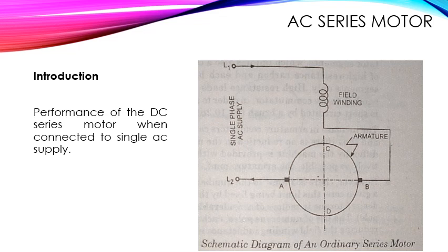Got this? So as they are placed in space quadrature, small current and abnormal voltage drop occurs, and that reduces the output and power factor to such a value that makes the motor impractical. Now the fourth reason is when a series motor operates on DC supply, it develops rotational EMF in conductors.